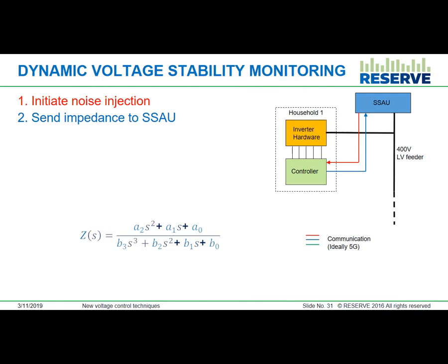It sends not only this but also the inverter's self impedance, or its own output impedance, to the substation, because as we know, in order to evaluate stability, we need the grid impedance and the inverter's own impedance, the ratio of the source and the load. So the inverter measures the grid impedance because it's unknown and sends it to the substation, and the inverter knows its own impedance mathematically because it depends on its operating point, its control parameters, and its physical filter parameters. So it can be mathematically formulated, as I showed in one of the previous slides.